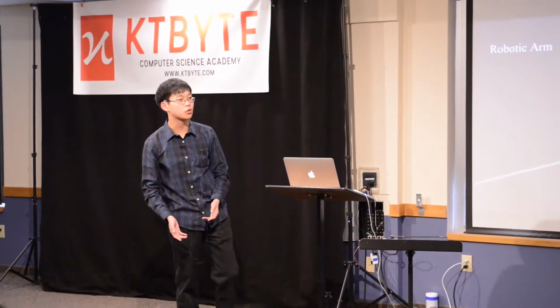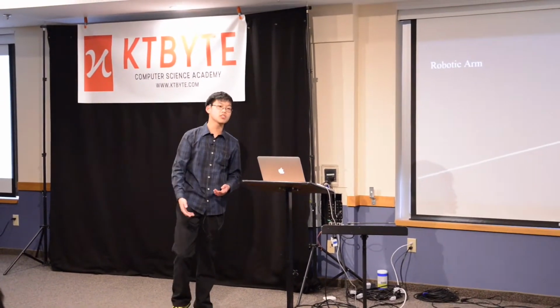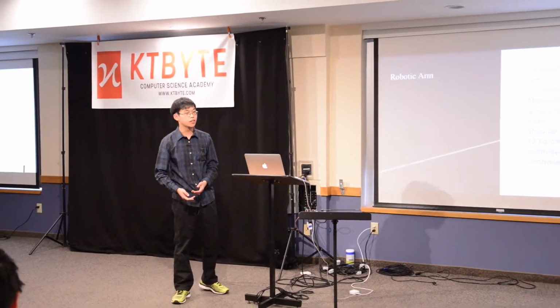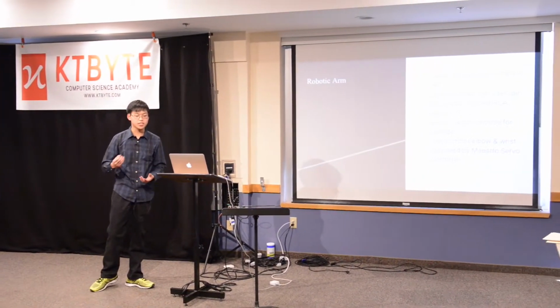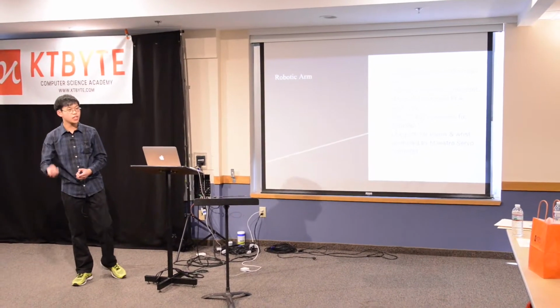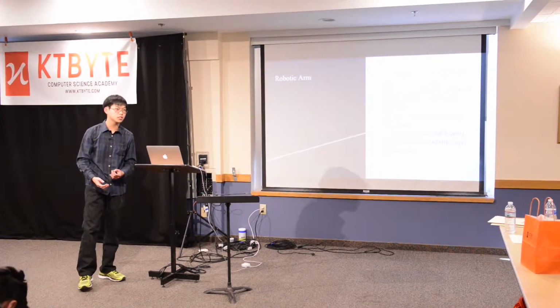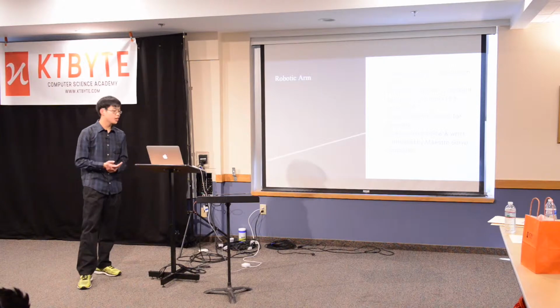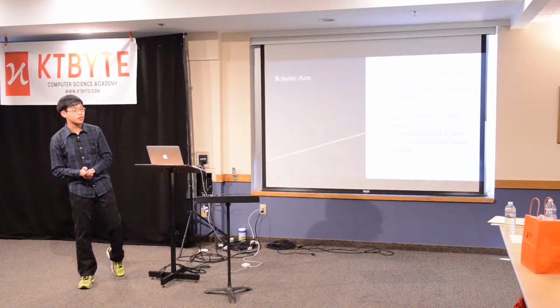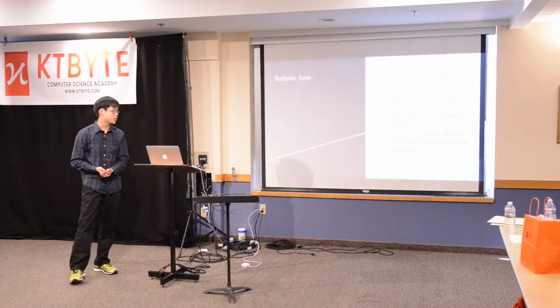Currently, commercial servos aren't able to hold a very heavy load. The strongest ones that I have are 17 kilogram-per-centimeter servos, which on an arm length of about 30 centimeters is about 500 grams of total weight on the arm. So in order to make this arm work as efficiently as possible, I've had to go through a lot of work designing and figuring out a method of saving weight while still keeping the robustness that it needs. What I settled on was a mix of acrylic, carbon fiber, and 3D printed materials in order to help with the mounts.